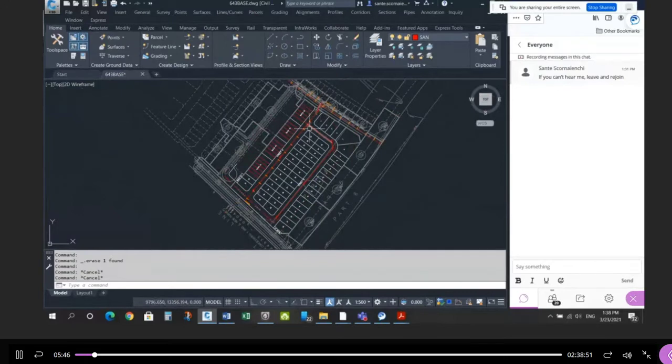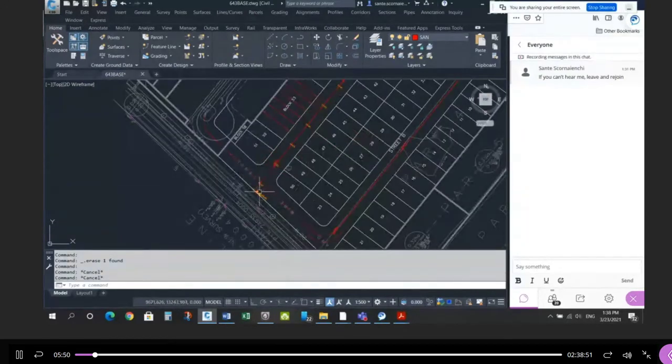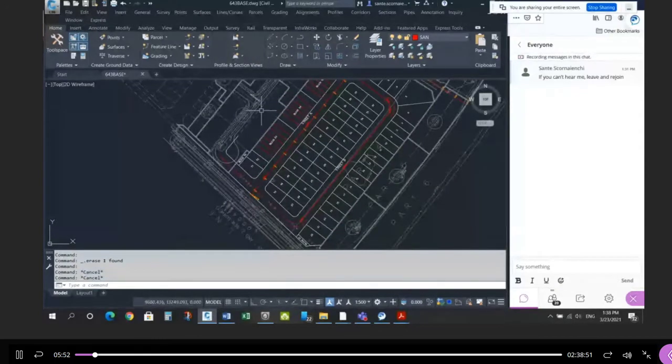And they appear in a couple of different spots, right? So this elevation on both street A and street B, this intersection elevation both on street A and street B, and this intersection elevation on street B. So there's 4 marks for those values, okay? The station values had to be correct as well. It's really the vertical we're playing with, right? We wanted to make sure that the elevation was in the right spot.